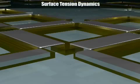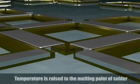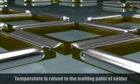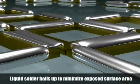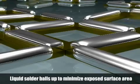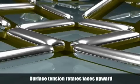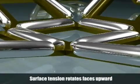Now we'll see how this force is used in self-assembly. The temperature is raised to the melting point of the solder. The liquid solder then balls up to minimize its exposed outer surface area. And finally, the surface tension force rotates the faces upward.